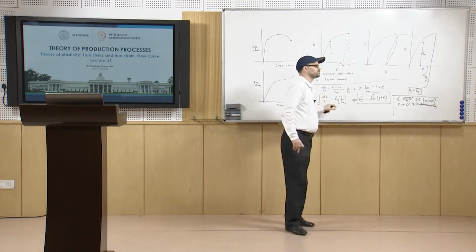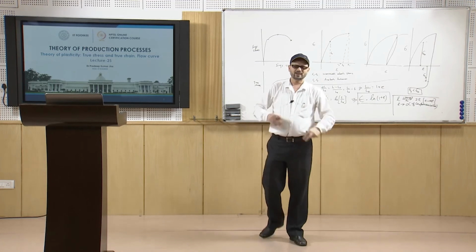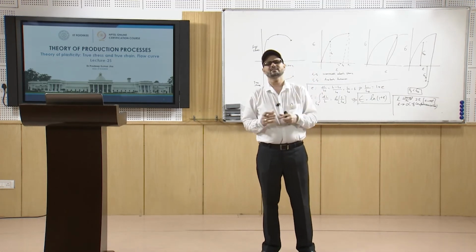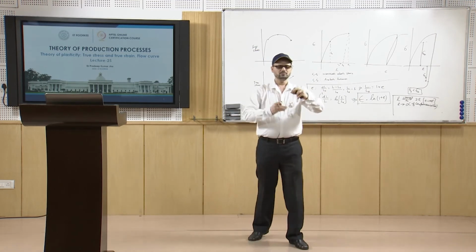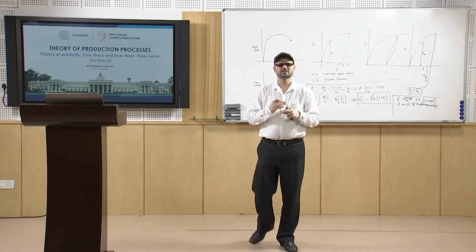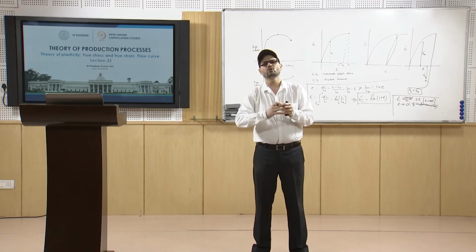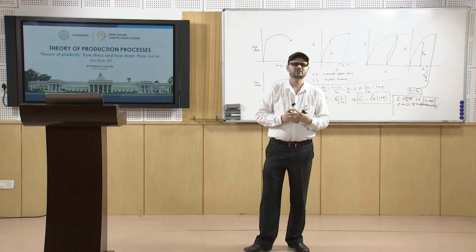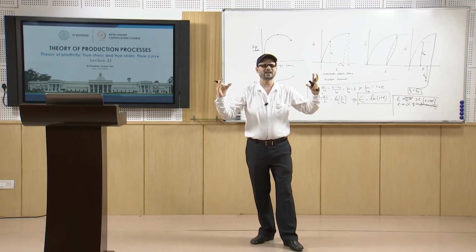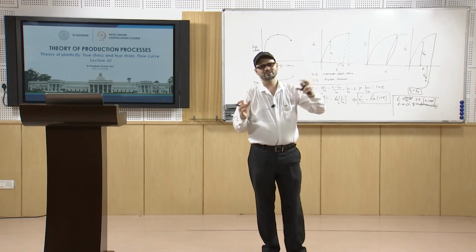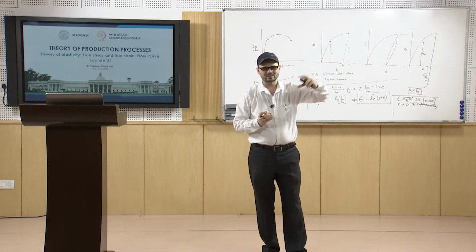this true strain concept. We can also see that if you take incremental steps of strain, suppose one bar is increased to a certain length and you go for 2 or 3 repeats, the final engineering strain will be different. You cannot say that it will be the addition of all of those.